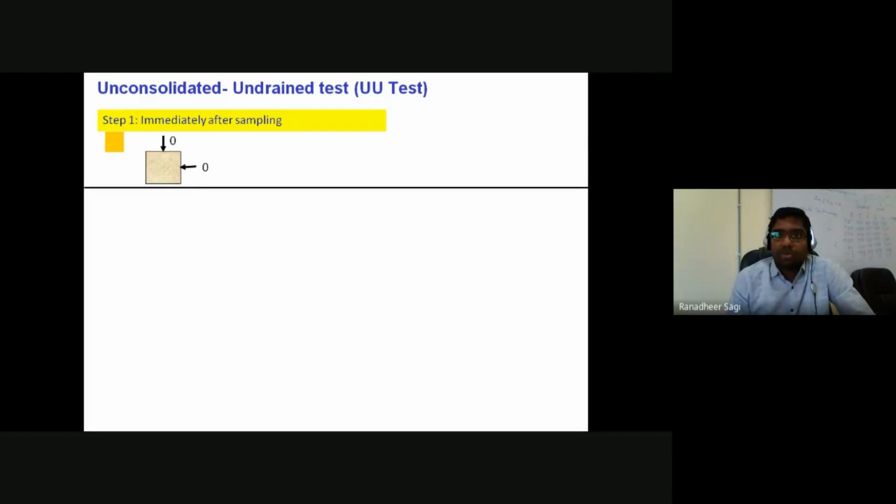Why is that negative pore water pressure coming into the picture? Even in the case of over consolidated soils, when we said the soil is over consolidated or dense, when the shearing is happening, the volume is increasing. Due to the increase in volume, the subsequent pore water pressures building up in the soil are no more going to be positive pore water pressures. Rather, they are called negative pore water pressures. Here also it is a similar phenomenon.